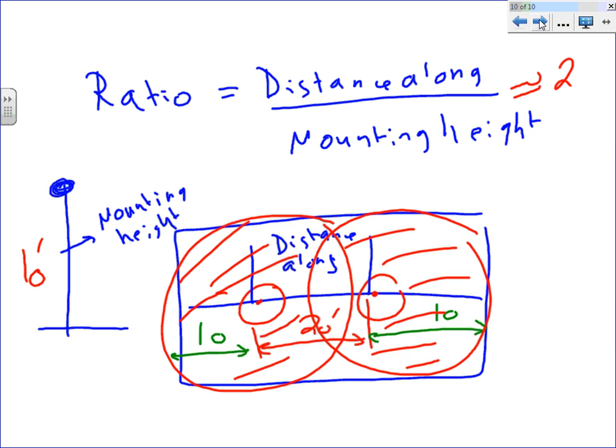Why is it important, guys? Like here, if you're doing schools, why do you think these lights are right here, right above the board? Because you need vertical light so you can see. Schools, manufacturing places where people have to read anything on the wall, certain factors will require a certain foot-candle right on the wall so people can see what they're doing. Take into account wall coverings, like reflectance. Yes, yes.